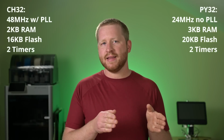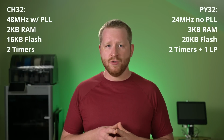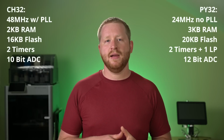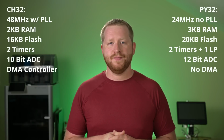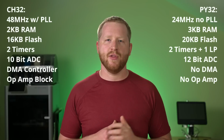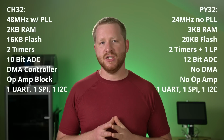Both parts have one advanced timer and one basic timer, but the PY32 has an additional low-power timer. Both have ADCs, however the PY32's is 12 bits and the CH32's is only 10. If you're sampling that data really quickly though, and you don't want to load up the processor, then you're going to find the DMA on the CH32 very useful, but you don't get that on the PY32. The CH32 also has a built-in op-amp, which, if you need it, could reduce your bill of materials in comparison with the PY32. For connectivity, they both have one UART, one SPI, and one I2C, but there's a caveat for the CH32.